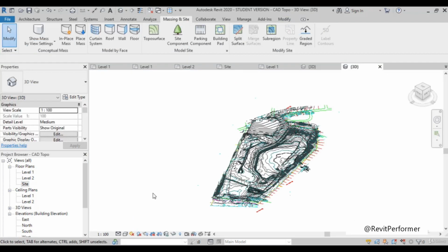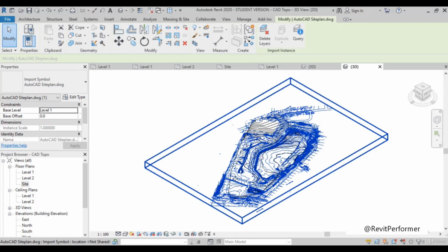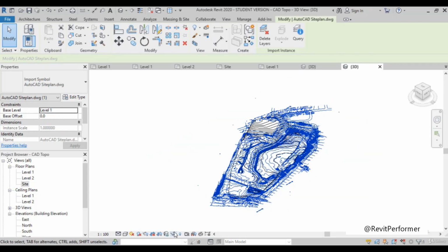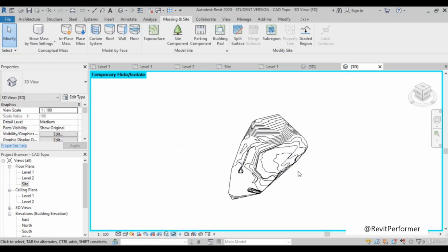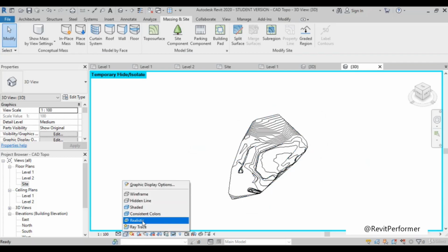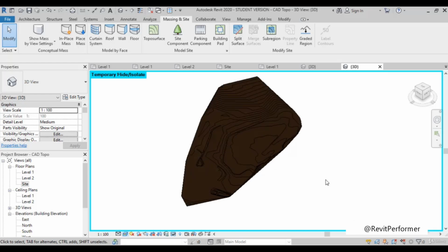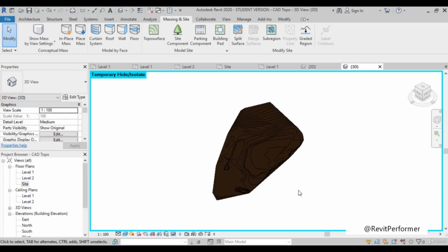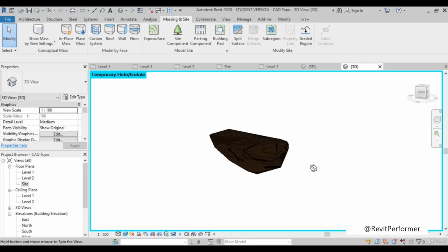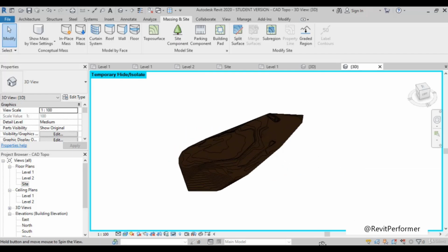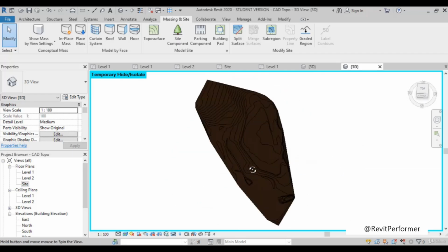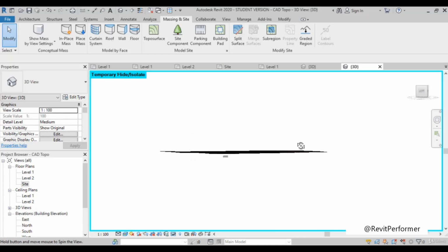After putting in 3D view, selecting this whole, I want to use this here, this hide element. Can you find it? Okay. Look, I'll show you how it looks. This is a realistic view. Okay. Go ahead and put in realistic. Now you can just use this and you can see the topography here, in the 3D view. When you go here, you can see the labels also.